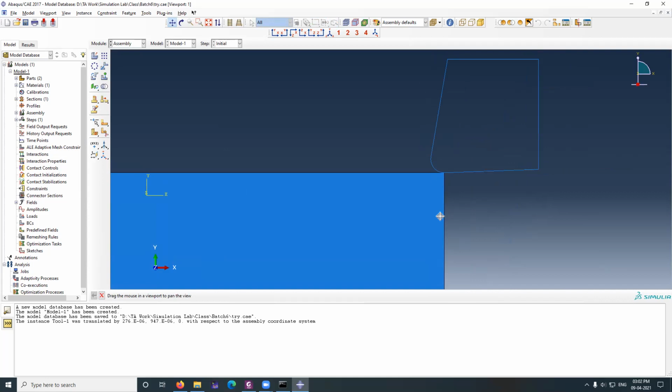Okay, if my RTS has to be 2, then I have to move this tool by 120 microns downwards. Before moving this tool downwards, I don't want the tool to touch right now, so I want it to move some way away from here arbitrarily. So let me move it. Move this tool, done. You don't have to give any point, just whatever starting point, give 0, 0, enter.